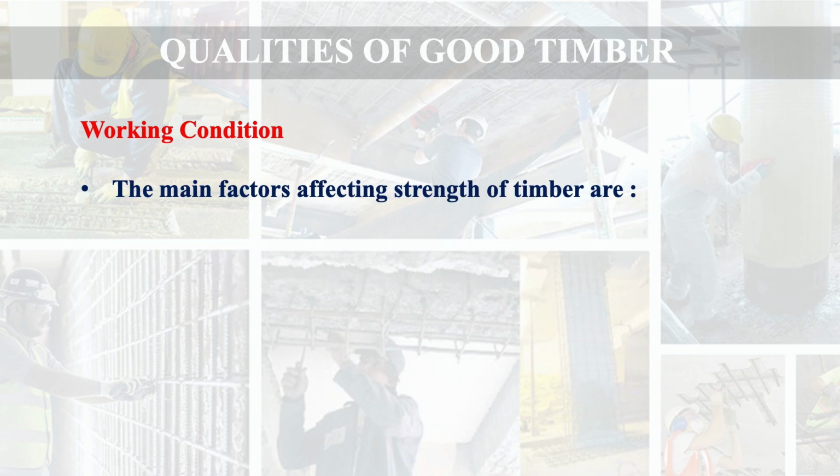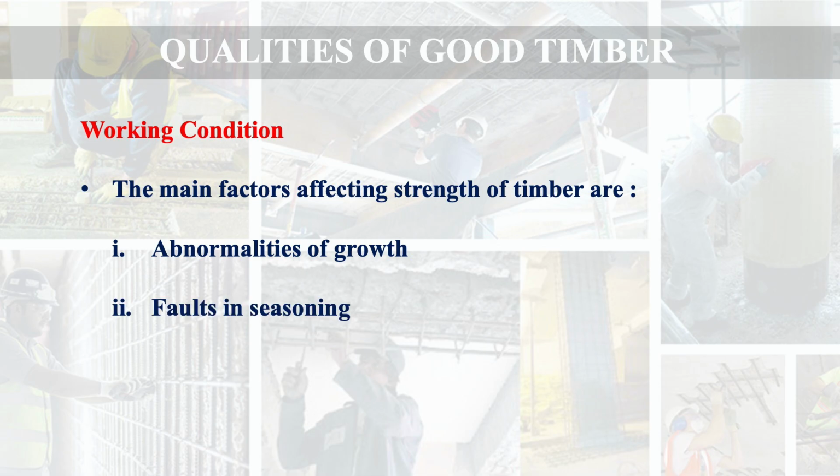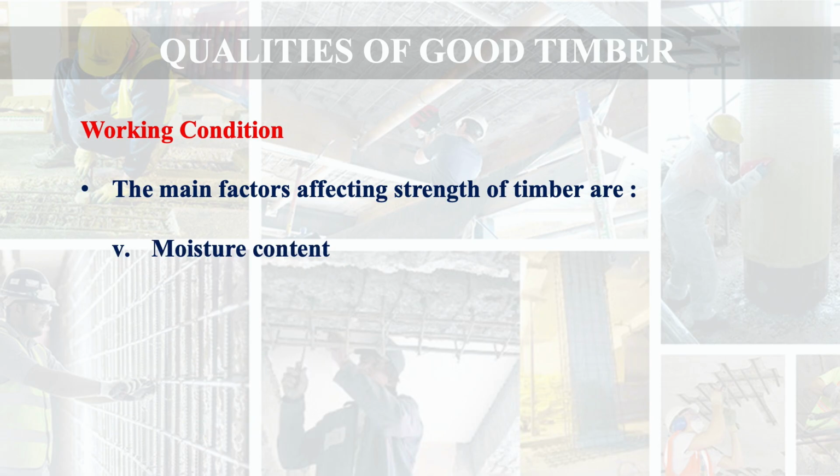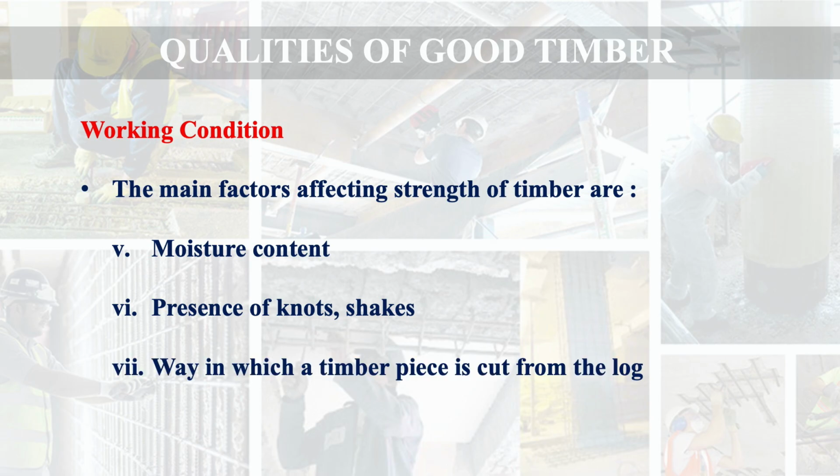The main factors affecting the strength of timber are abnormalities of growth, faults in seasoning, invasion of insects, irregularities of grain, then moisture content, then presence of knots, shakes, etc., and finally the way in which a timber piece is cut from the log.